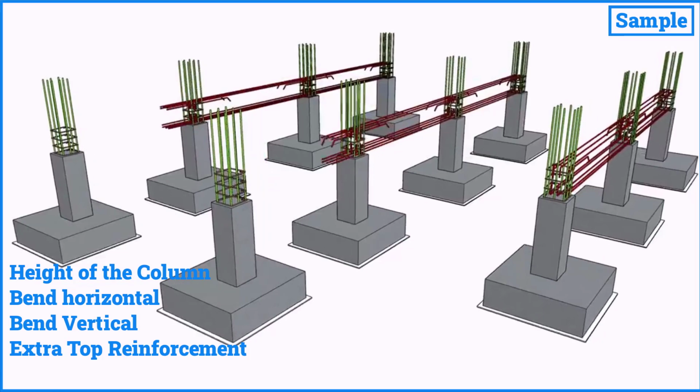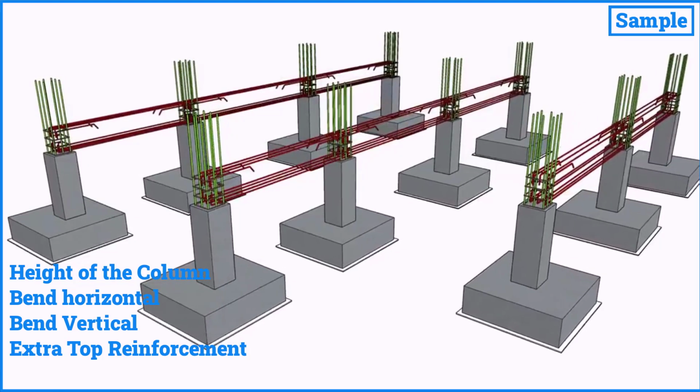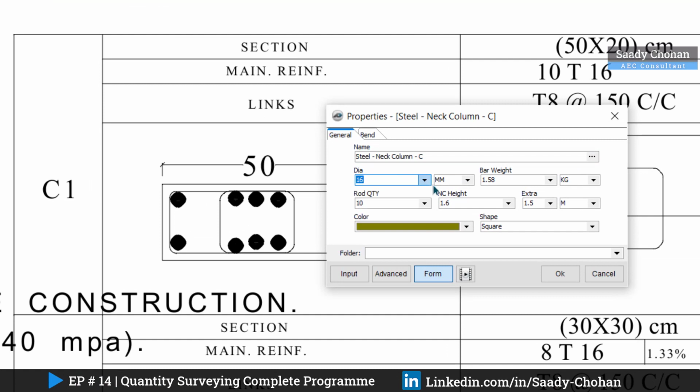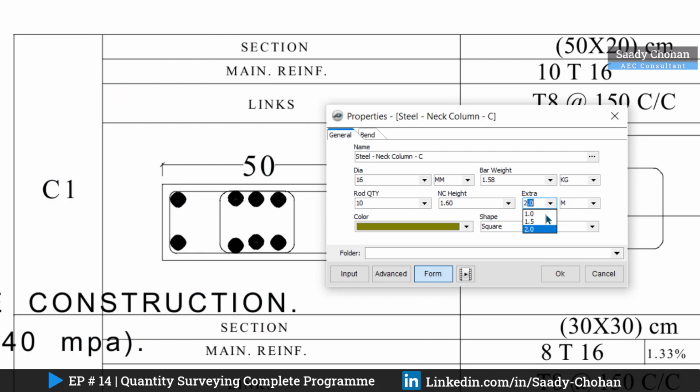Now either you use the Excel sheet or the PlanSwift software or the calculator, it doesn't matter. I will use the PlanSwift template. It's very powerful, you will see now. So what is the dia size? I can mention it's 16. The bar weight, number of rods, it's 10 quantity. The height is 1.6 as per the section. And extra, how much extra do you want to consider after the slab above? So I can consider here 1.50. According to the section you can add more, maybe 2.0, or depends.